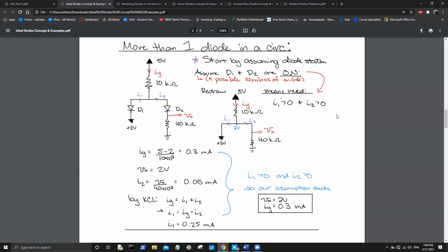So fundamentally, the method you use to solve these problems, it looks like, is all about your assumption table, which is what he did for the 3s. She simply went right to assuming they're both on, because odds are that's the main line solution. But depending on the circuit, the resistances, the voltages, you could also have another combination that is feasible. So that's why you have to test all. And I feel like the on position is the easiest place to start.